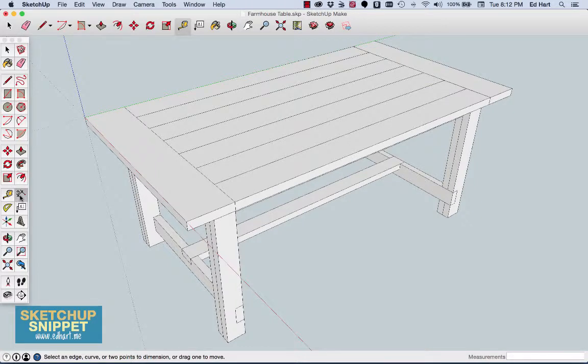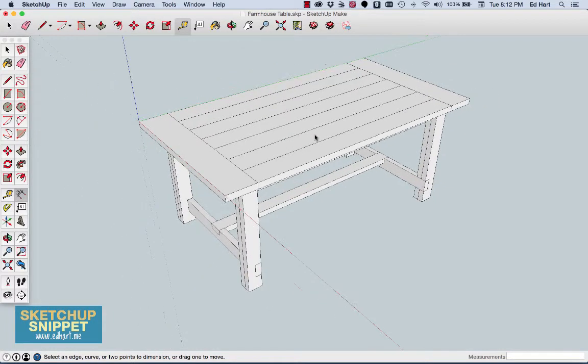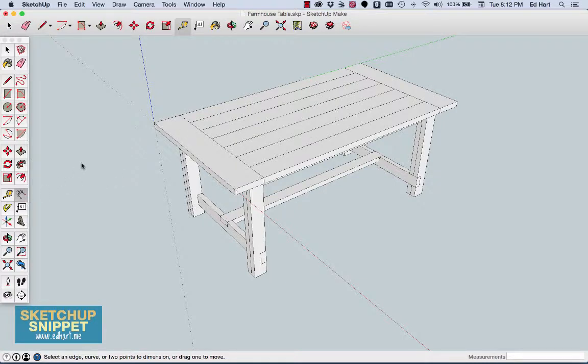You've probably seen this a bunch, and this is how you draw the measurements on your model. I'm going to zoom out a little bit just using my scroll bar. To use the Dimension tool, it's just like the tape measure tool. Set it at a corner, click and drag, and now you'll see it will show you the measurements of whatever you're measuring. Click the mouse again to end that, and now you can drag that up or out to the side or however you want. If you hit enter again, it will set that dimension, and that's so helpful if you want to illustrate all of the different areas of your model and show exact dimensions.